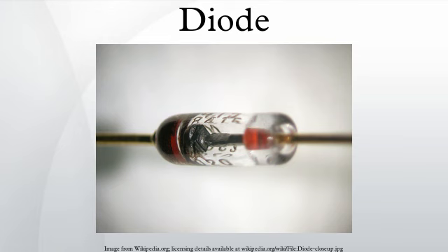Avalanche diodes. These are diodes that conduct in the reverse direction when the reverse bias voltage exceeds the breakdown voltage. These are electrically very similar to Zener diodes, but break down by a different mechanism, the avalanche effect. This occurs when the reverse electric field across the p-n junction causes a wave of ionization, reminiscent of an avalanche, leading to a large current.